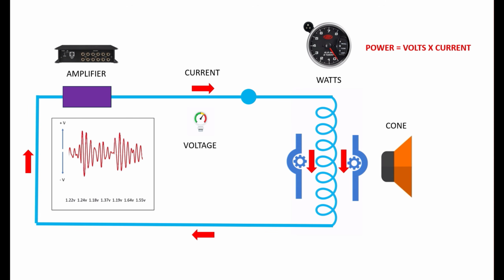So if you have a 100 watt speaker, that is the power rating of the speaker. It's how many watts that speaker can handle safely before you exceed its thermal limits. So if you push 100 watts into the speaker, fantastic, no worries at all.